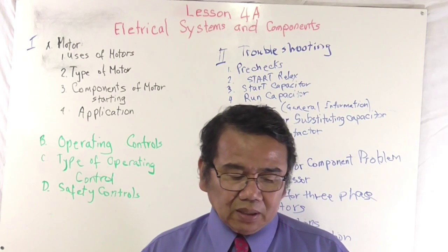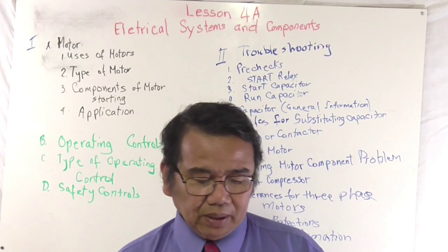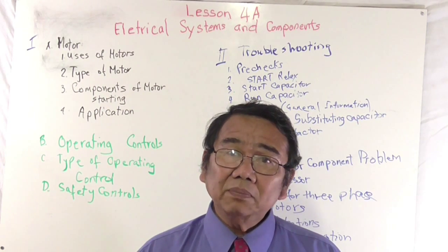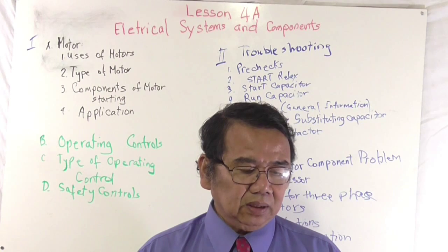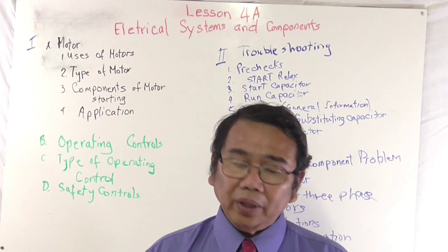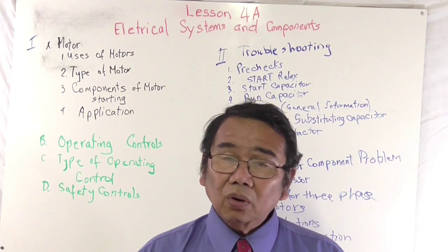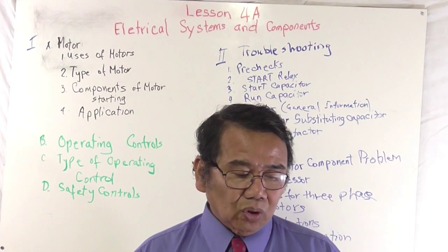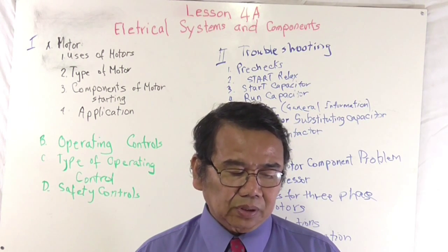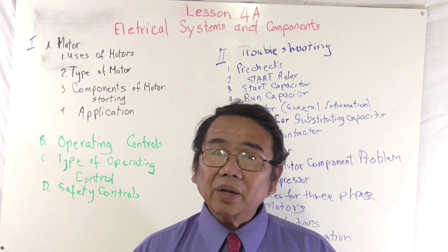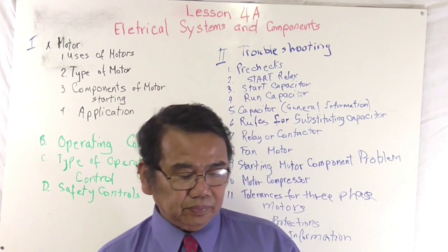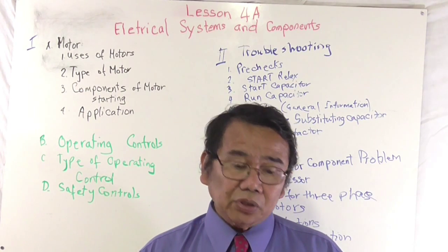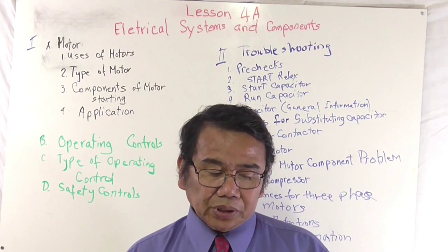Be sure you select the right capacitors for the right equipment as designed. A shorted run capacitor usually bulges. A shorted capacitor will blow out the small disc on top of the capacitor. Run capacitors are designed to remain in the circuit all the time. A start capacitor has to be removed from the circuit in a very short time, usually 1 to 3 seconds.